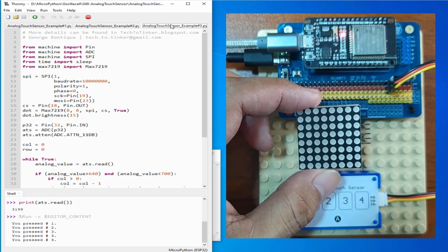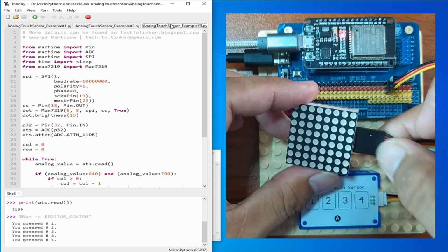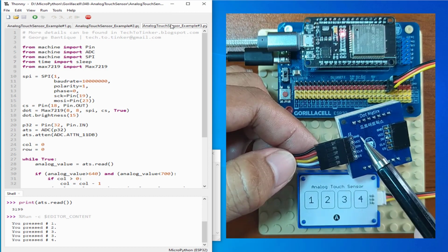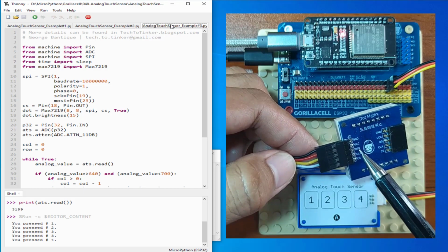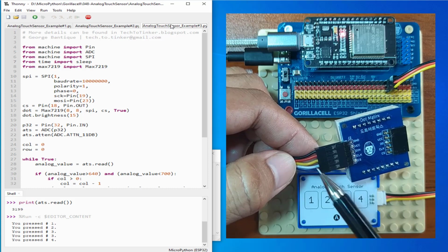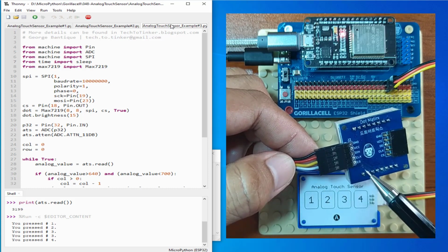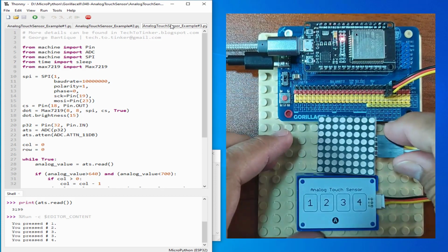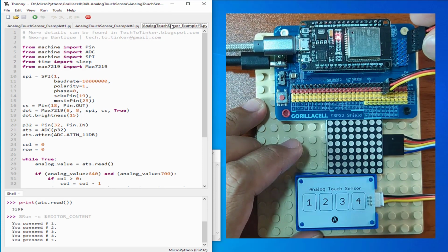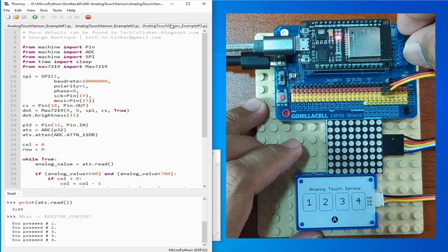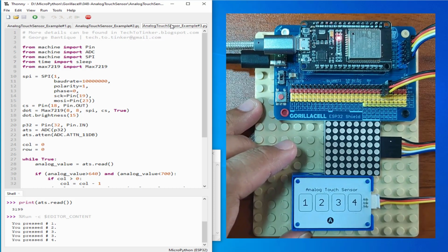First, connect a 5-pin 2-point jumper wires such that black is to the ground, red is to the VCC, yellow is to the data input pin, white is to the clock pin, and blue is to the chip select pin. Now attach the other end of the 2-point jumper wires to the dedicated SPI port on the ESP32 shield.